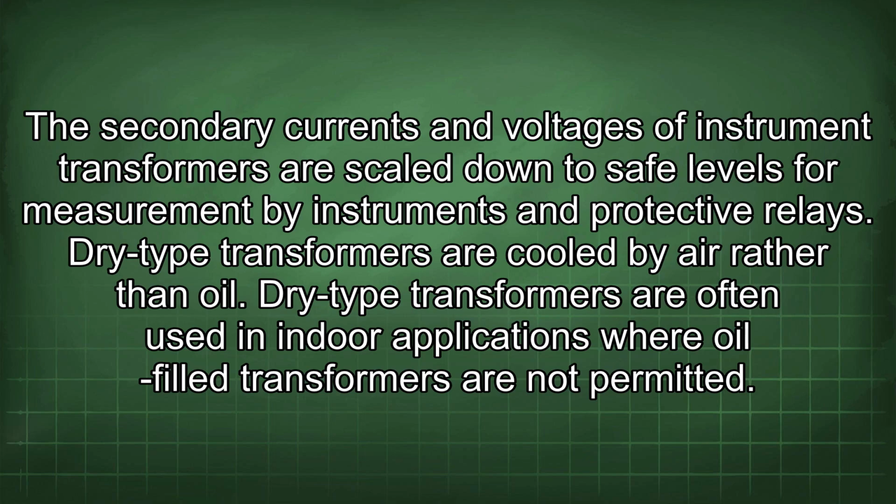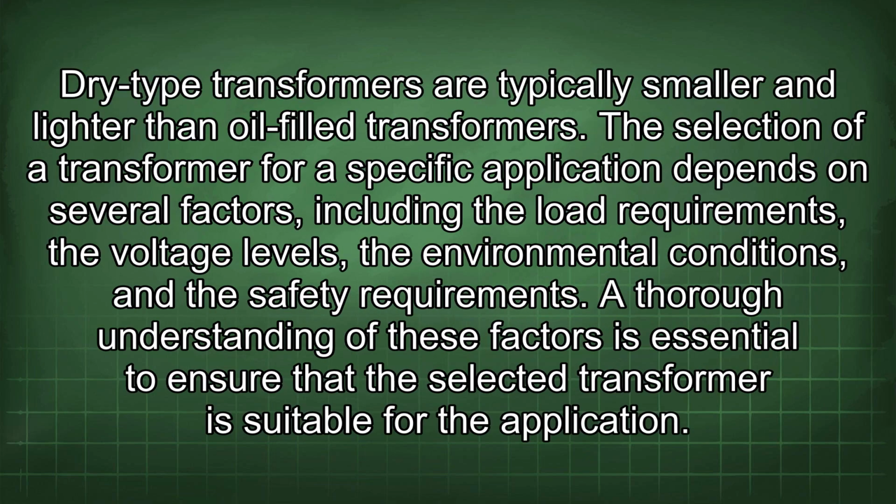Dry-type transformers are cooled by air rather than oil. Dry-type transformers are often used in indoor applications where oil-filled transformers are not permitted. Dry-type transformers are typically smaller and lighter than oil-filled transformers.